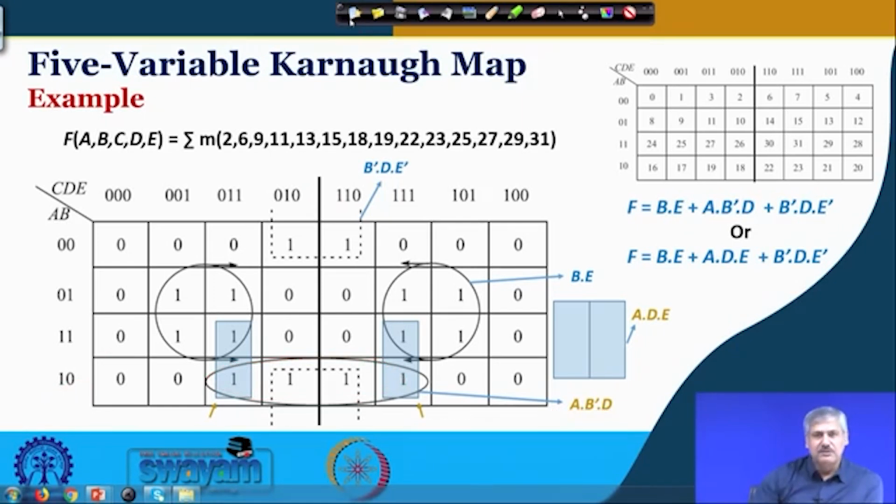The other thing which is not very apparent, but again if we consider the reflection, we can see that these two are logically adjacent, easily understood. But again it is against this particular axis, one is the reflection of the other. So, that way also this group of 2 and this group of 2 are logically adjacent. So, accordingly a group of 4 can also be formed, which is of similar size as the previous one we considered over here.